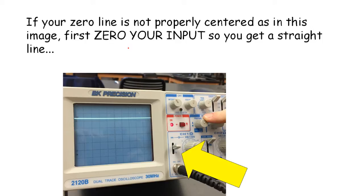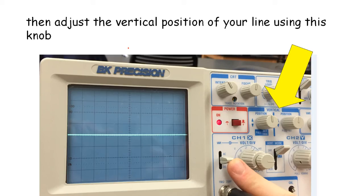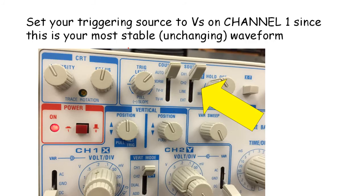If it so happens that your waveform is somehow off center, what you do is you ground your input right there. You put the input to ground, and then you adjust the position using this knob, as Michael is demonstrating here. Michael has adjusted this knob, even though he's pointing to this one now, so that that line went down to here. Once you get your channel zeroed, you can DC couple it again and look at your signal.